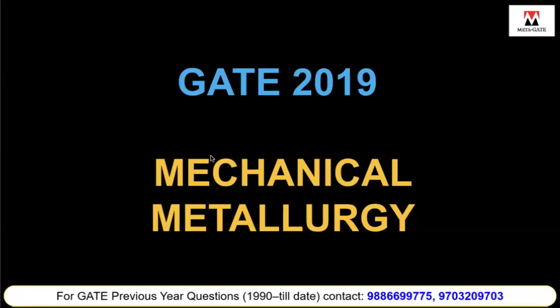Date 2019, mechanical metallurgy. During low strain rates, less than 0.1 per second, consider the deformation of metal at room temperature, the one that deforms by twinning mode. Generally, twinning mode deformation happens mostly in HCP metals, and slip deformation happens generally in FCC and BCC. So out of all these, magnesium has HCP structure.